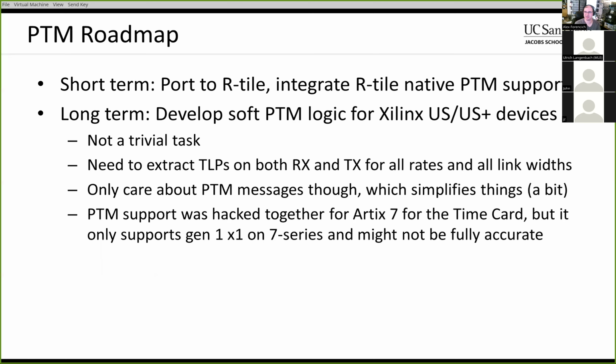And then the long term is to develop soft PTM support for Xilinx Ultrascale Plus devices. Unfortunately, this is not a trivial task because we need to be able to extract the PTM TLPs on both the RX and TX paths for all the rates, Gen 1, Gen 2, Gen 3, and probably Gen 4 as well, and all link widths, right, all the way up to by 16. We only care about the PTM messages though, so that simplifies things. So we don't have to care about really long messages. We don't have to care about link layer stuff, just the PTM TLPs.